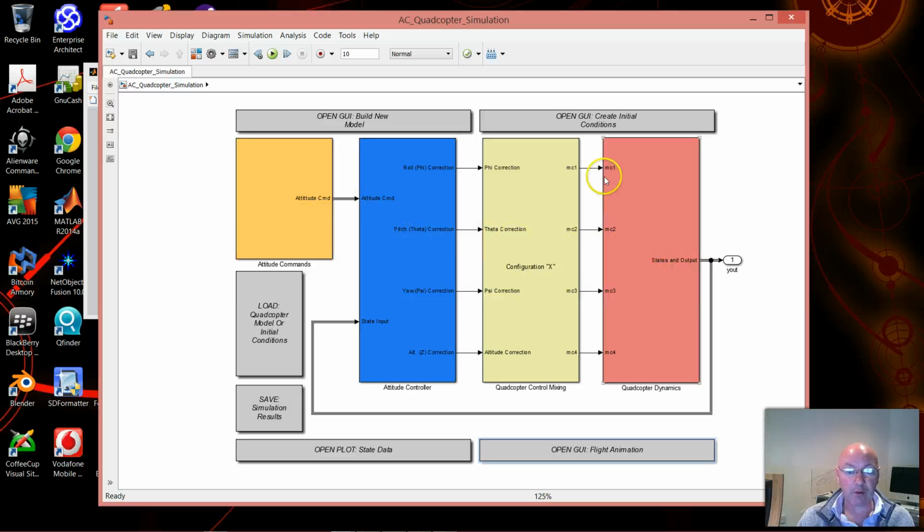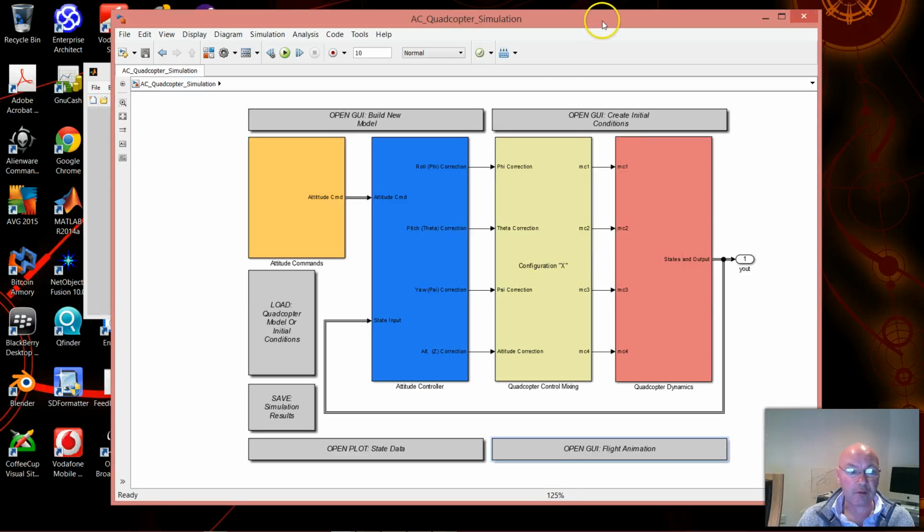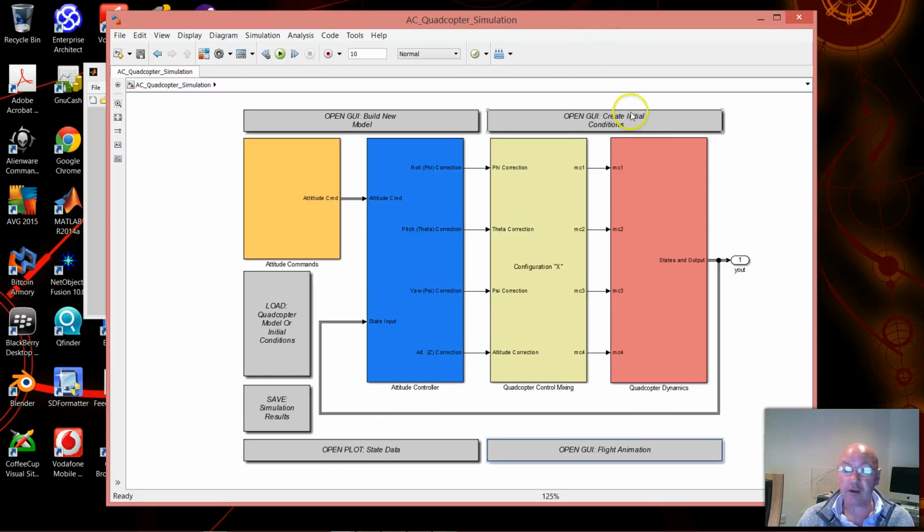The hardware is not capable of simulating models with variable steps. So there are techniques we can use to convert this model to put into the hardware, but it's involved, and it's much better if you start a model from scratch with the intention that you're going to generate code, which is what I'm going to do. But I'll probably use a lot of concepts from this model.